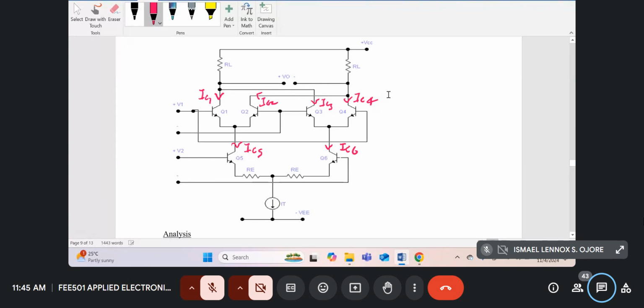Oh, I'm confusing myself. IC is beta IB. IE is beta plus 1 into IB. But if the beta is very high, that addition of 1 is small. So we'll assume that all the collector current goes to the emitters of the respective transistors.